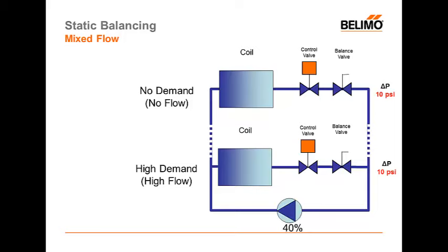Remember, at full flow, which we're going to assume we have here in our first zone, we wanted to take a 12 psi pressure drop at my balancing valve, but I don't even have 12 psi to use up here, and so we're going to run into trouble as we do this. The far zone has no pressure in it. The closest zone, we're supposed to have 4 psi on our coil, but we'll never get it because we're supposed to have 12 psi on our balancing valve, but we can't do that. And what happens is the balancing valve winds up choking this coil. And what really winds up happening is that we can't meet the demand in this space.